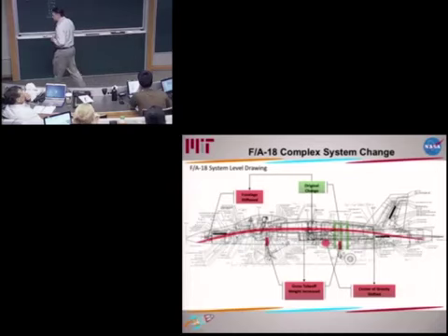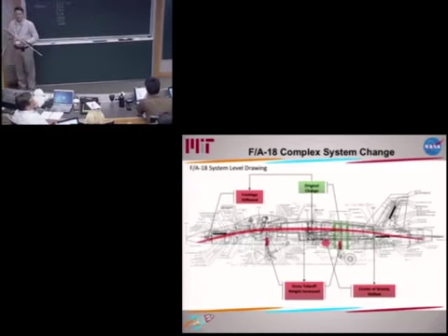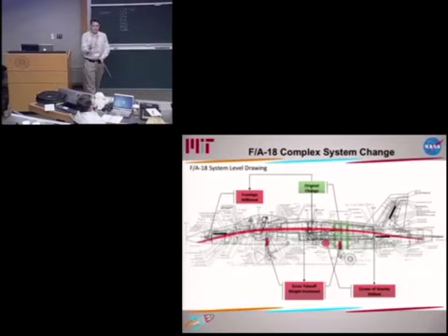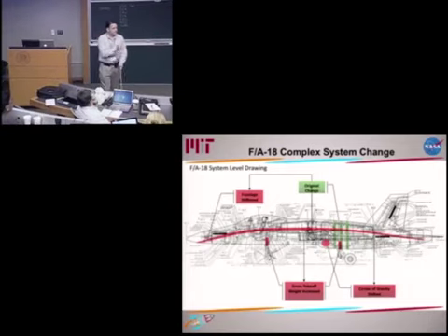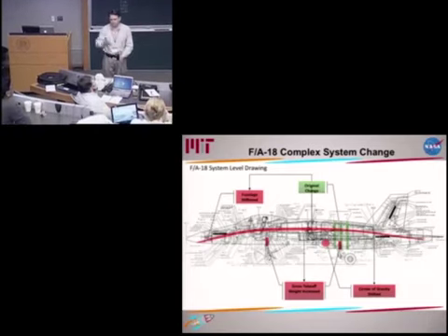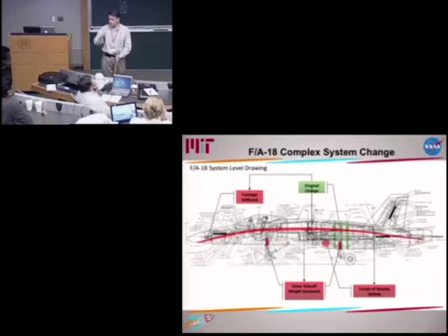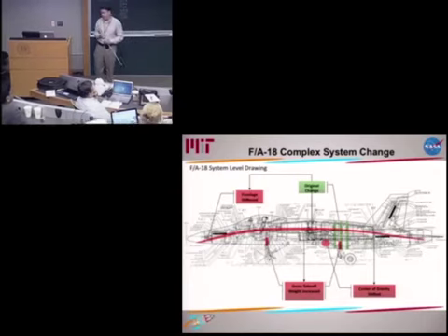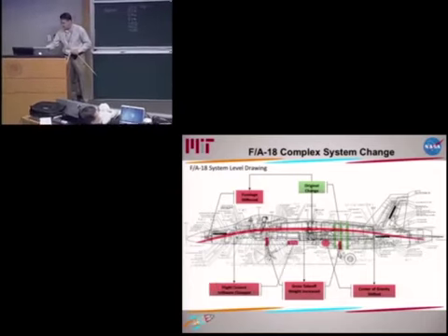The problem is that in a fighter airplane, in the flight control software, when the pilot actuates the stick, you have some filters in the control software, some notch filters, because if you put a step input into the aircraft, the energy at those natural modes of vibration could be destructive to the aircraft. So you have to reduce the energy at those frequencies.